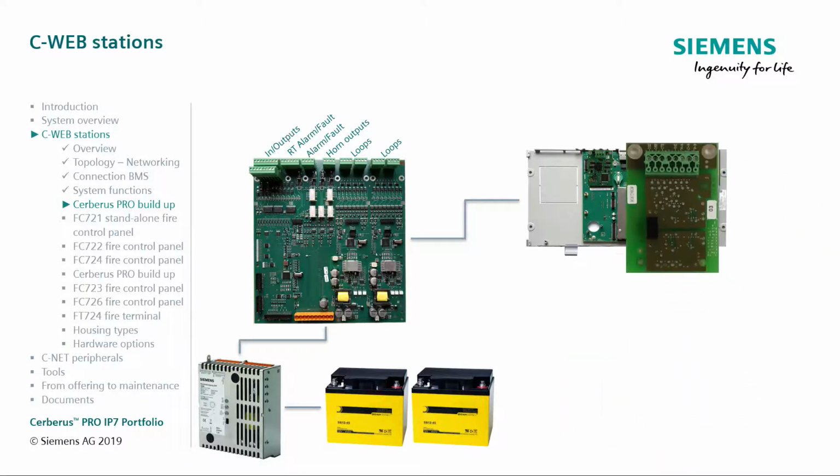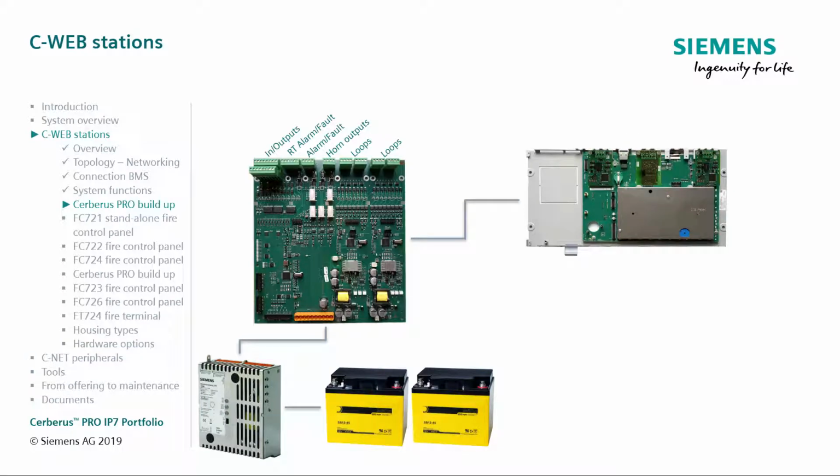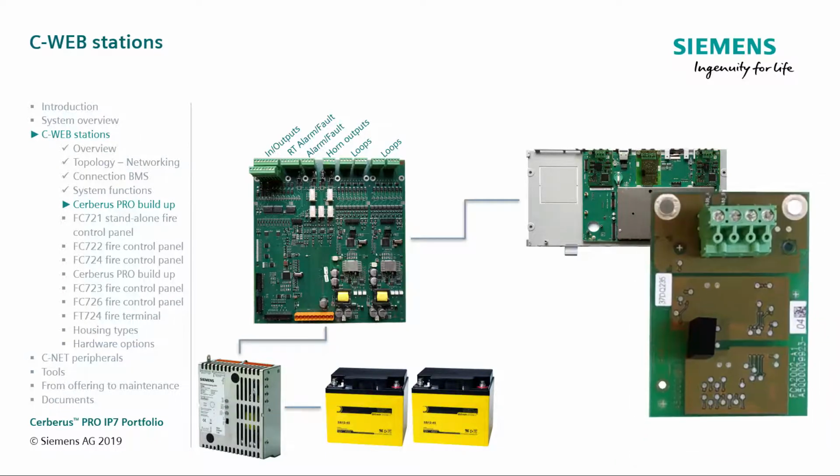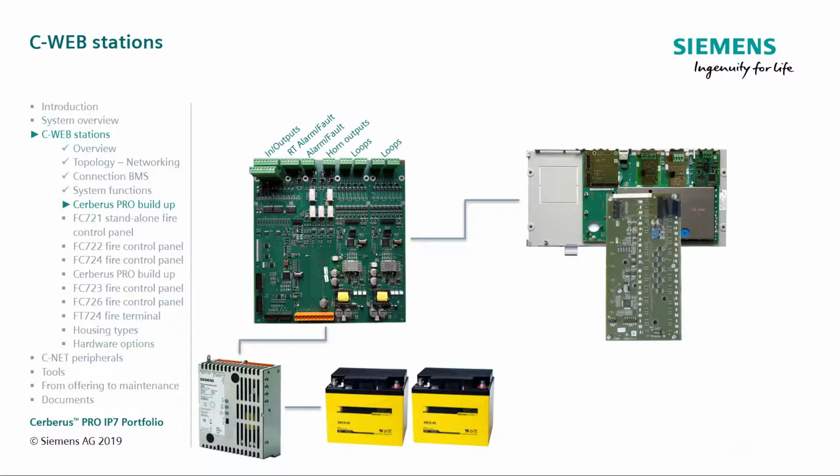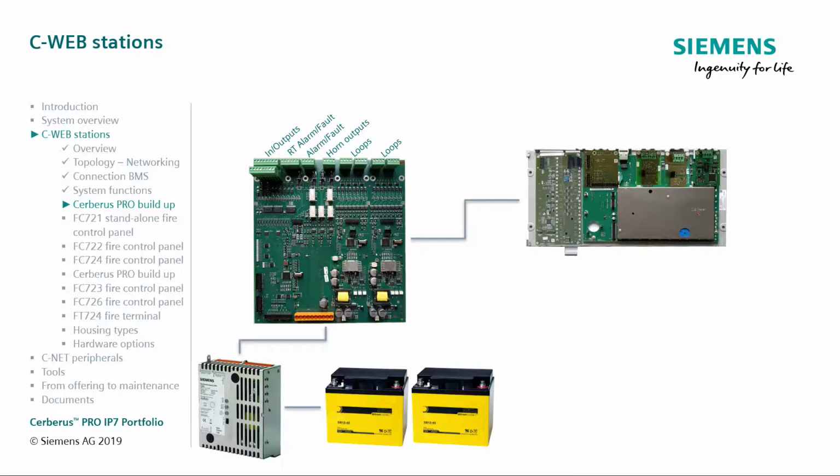The RS-232 module is for use when the printer is selected. The RS-485 module provides alternative serial communication to third-party fire peripheral modules. To connect the FN2010 network switch to the panel, it would be functional to use the MONET module. Additional to the indication options of the panel, you can order a different PMI with 24 LED indicators.